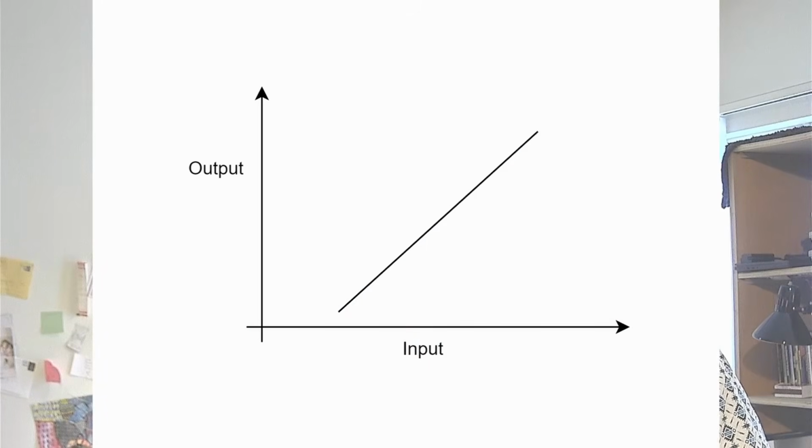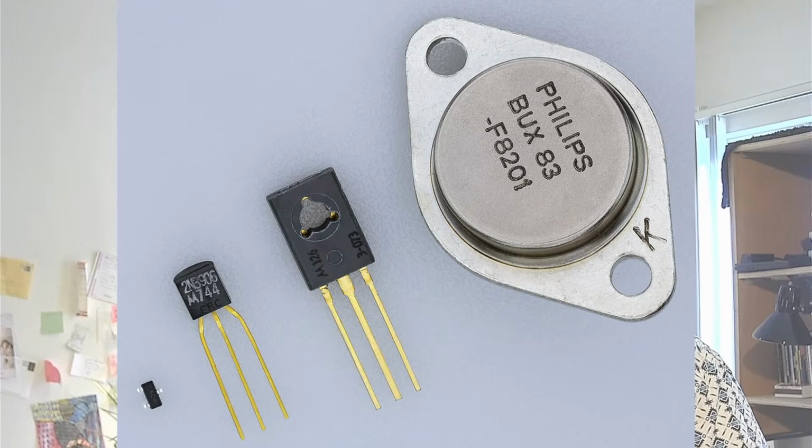Generally speaking, analog circuits will map some kind of a voltage to some other kind of a voltage, or a current to a current, or it can go the other way. You can map a current to a voltage, voltage to a current, you can go either way. Most commonly, an analog circuit will perform linear algebra. Most of the time, analog circuits behave linear. There are, of course, nonlinear circuits. If you're going to design something using discrete transistors, those are quite nonlinear. You have to bias them to the right area.